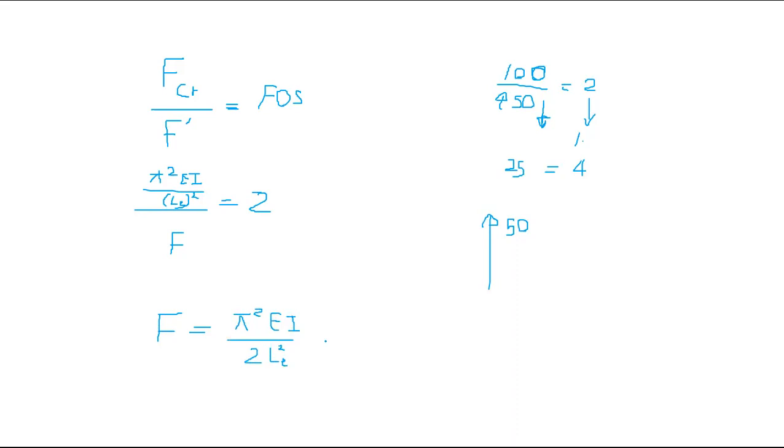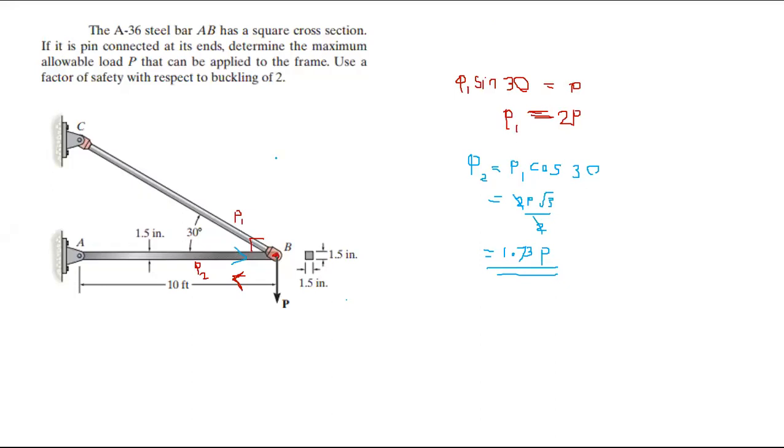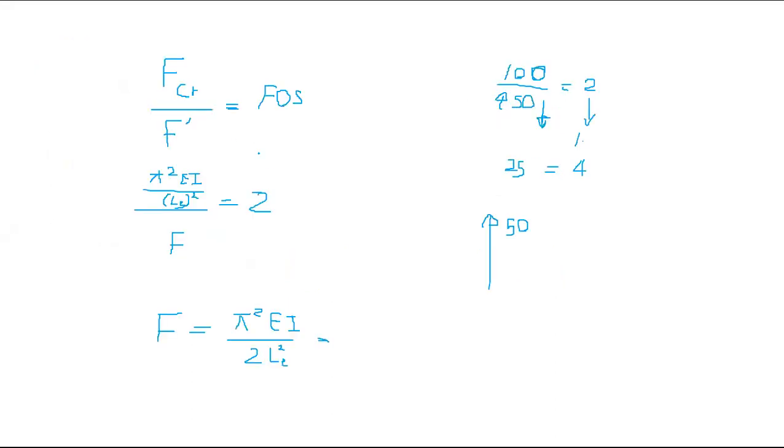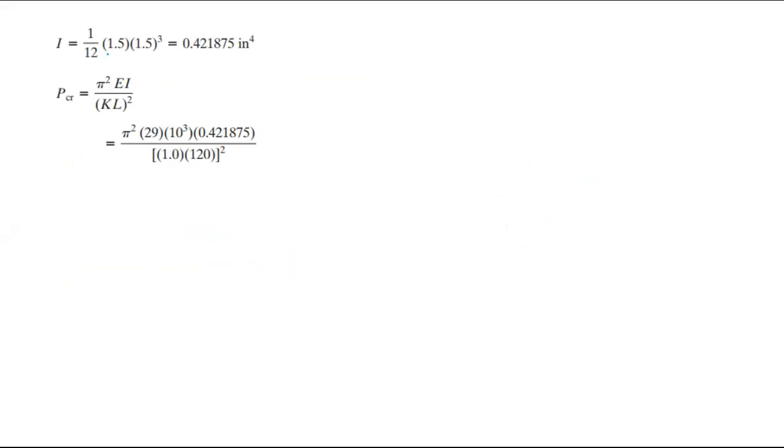For A36, you can determine the buckling load. You know the E value from the tables, and the section is given so that you can calculate the I value.